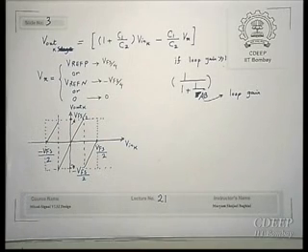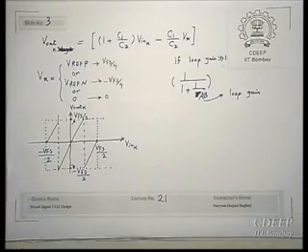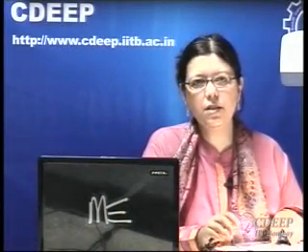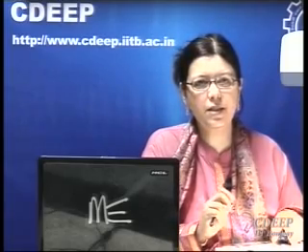Okay, so till now everything is according to what you have learned. Now we want to implement this again using a similar switch cap configuration. One thing I didn't find in this configuration was offset compensation. You will see that it doesn't have offset compensation, but we can easily change the arrangement of switches, the way we did for the example in the class, and make it with offset compensation. In the paper, offset compensation is not considered, but in your project you do.